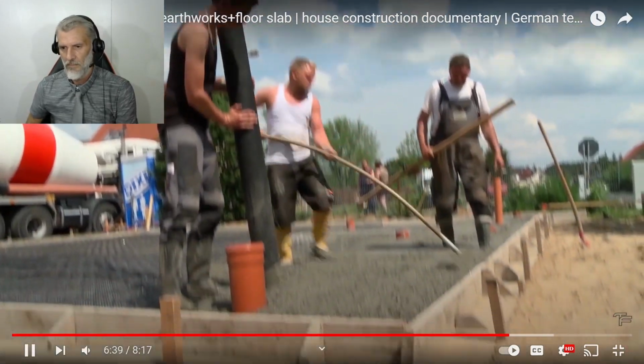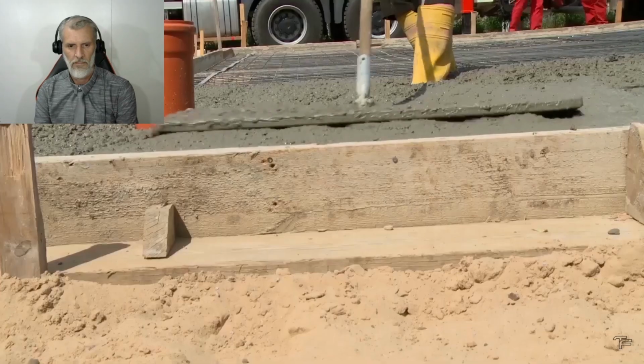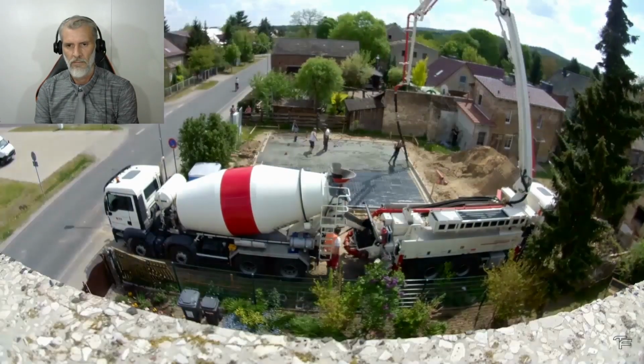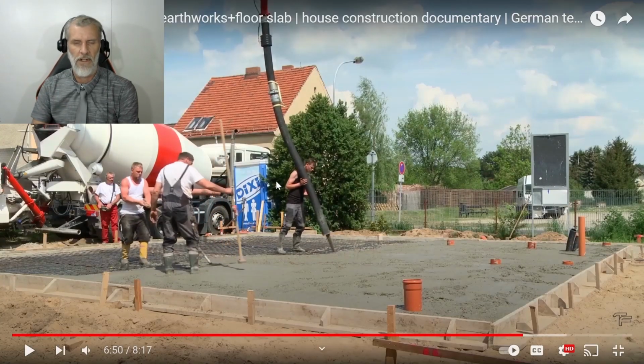It is important to evenly distribute the concrete and prevent air pockets. Therefore, poke again and again with the scraper. We have a vibrating machine, which is like a noodle. We do exactly the same thing. We put our rebar up on top hats, so there's a gap between the rebar and the ground, so the rebar is right in the middle of the concrete.